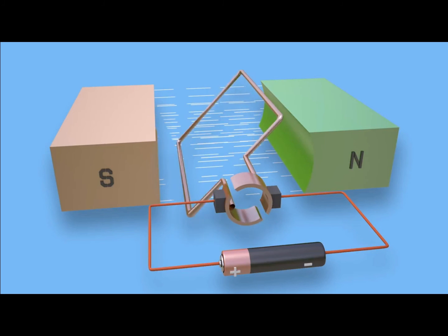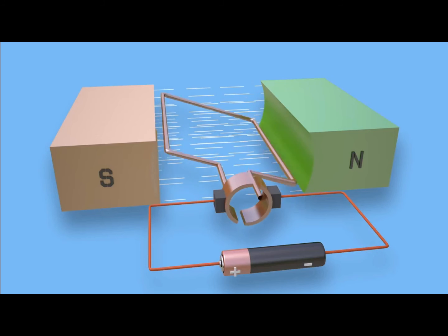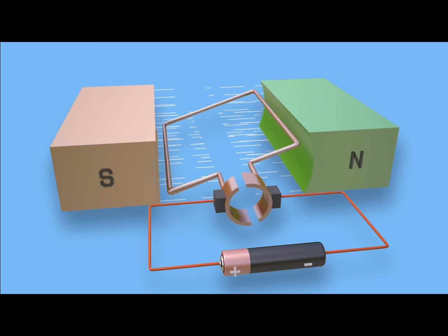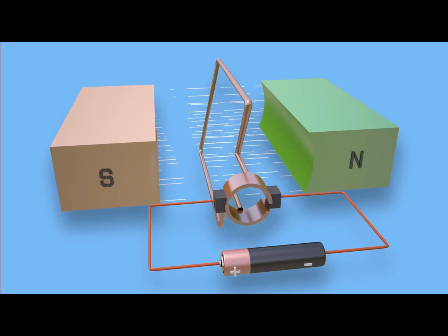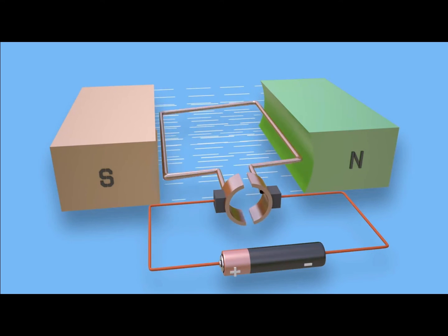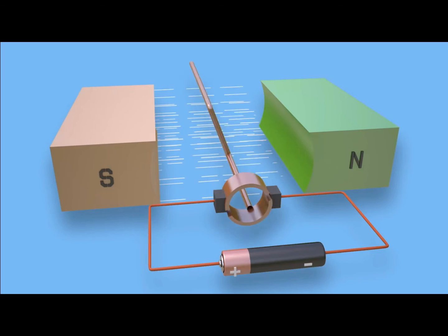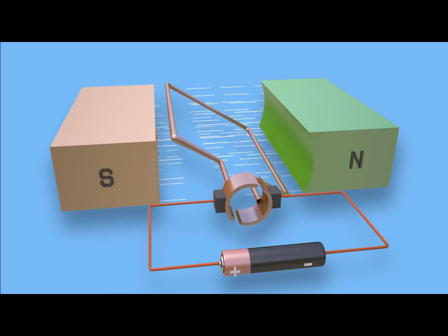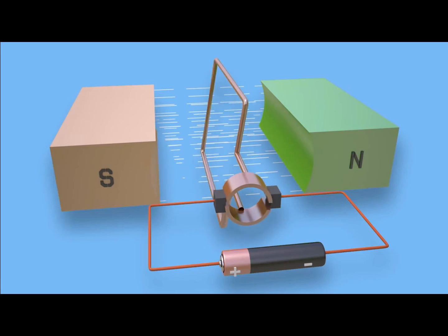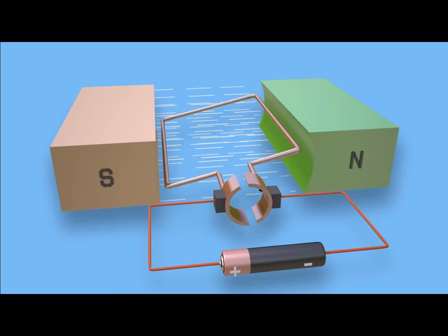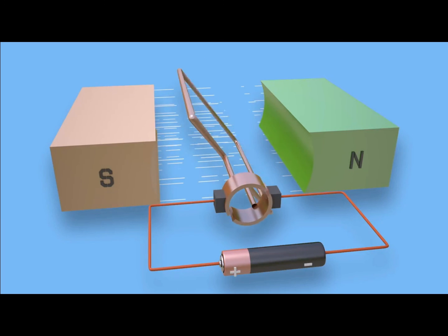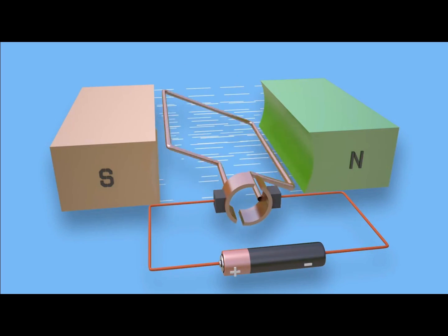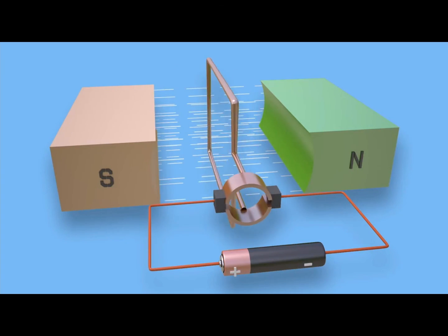From this explanation we can conclude that in this model, whichever conductor comes near the south pole experiences an upward mechanical force, and near the north pole it experiences a downward mechanical force. Doing this continuously, the mechanical force will keep the coil rotating even if the battery is not connected. This is how the application works, doctor, and the rotation follows the same principle as the elementary model we did for our EMT assignment.